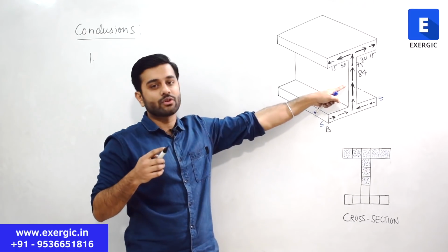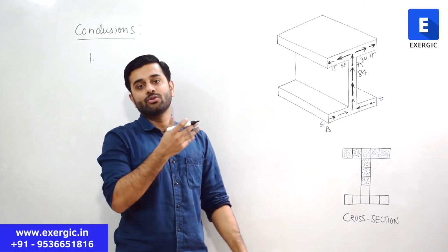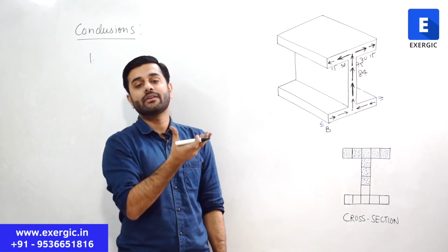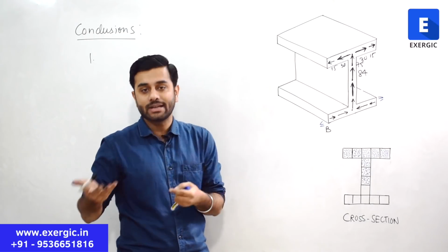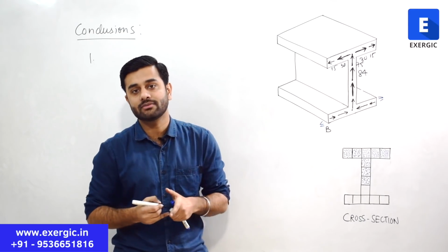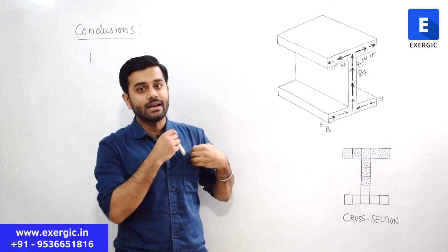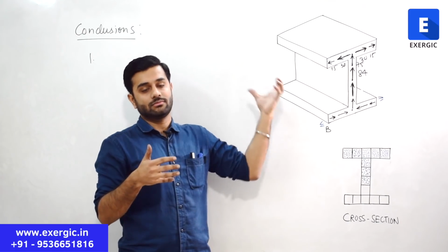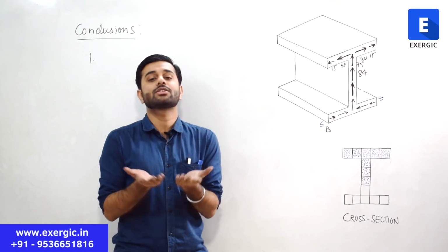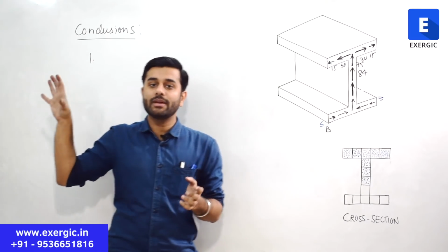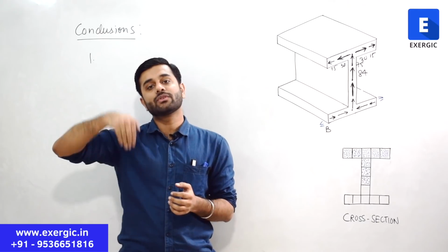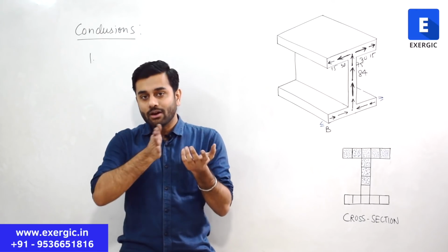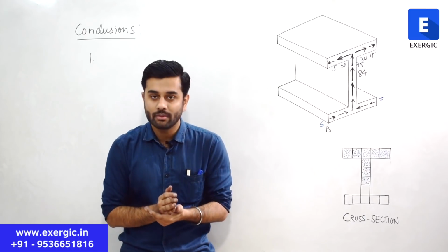These are the values of forces, right? You can know the value of shear stress by using the area. Shear stress is shear force divided by area. Using the area, you can do that calculation. We will discuss that in the further topics. But please understand that there is no net horizontal shear stress due to these discussions. And obviously, why should it be there? If you recall the beam, we applied only the transverse shear stress, which was vertical. So there is no point that a horizontal resultant shear stress will come into action.